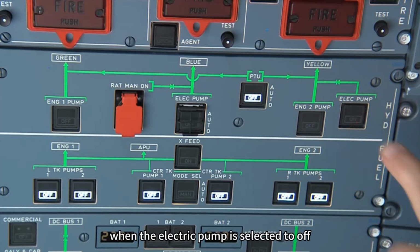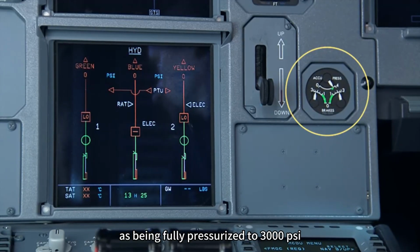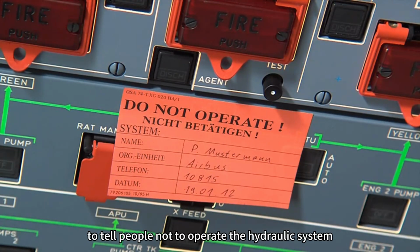When the electric pump is selected to off, the triple indicator should show the brake accumulator as being fully pressurized to 3000 psi. Place a warning notice to tell people not to operate the hydraulic system.